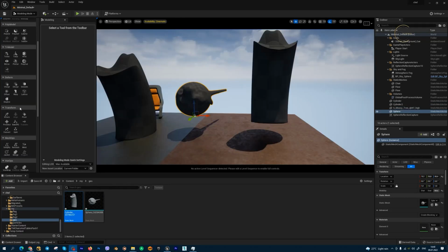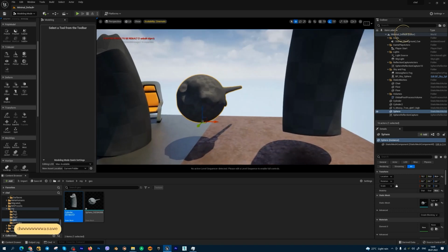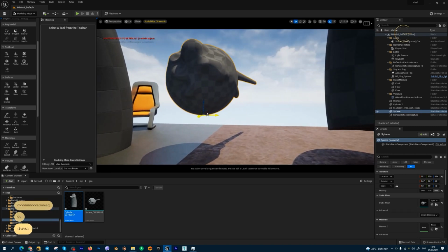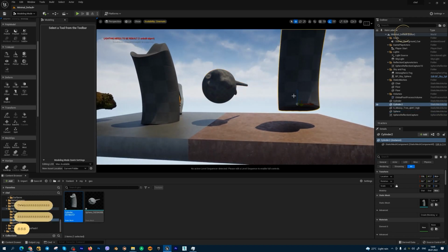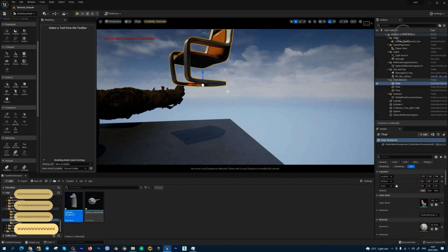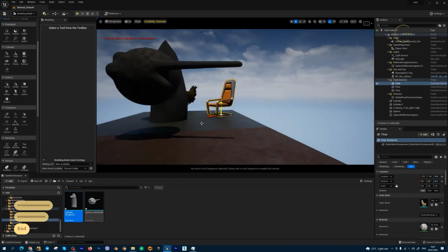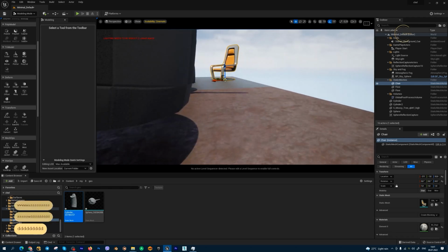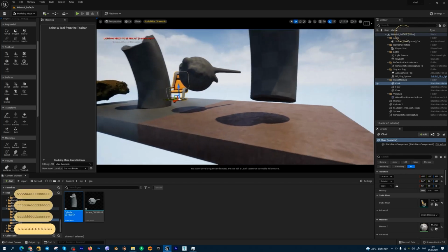Next very powerful tab is transform. So we have pivot instrument for editing pivot any of your meshes. So best place for your pivot is center of your geometry and bottom part of bottom corner of your geometry. So if you select any Megascans asset or any Unreal primitive, we have pivot inside this point. It allows you using, for example, end button, put any object on floor, on ground. So this place is better place for your pivot in any geometry.